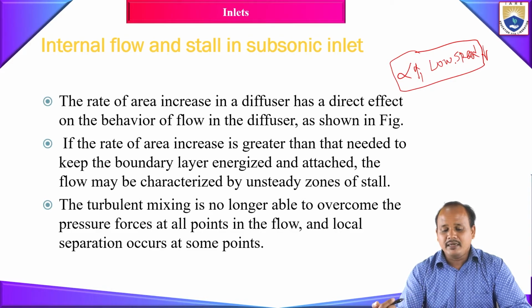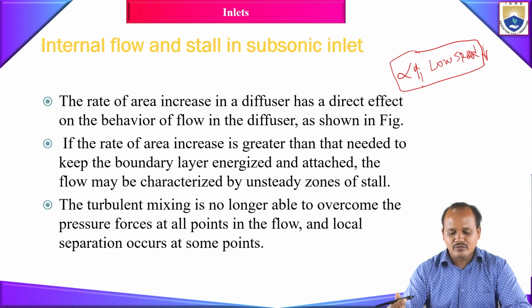Similarly, in the intake also, during your takeoff, we will have this flow separation problem, because during takeoff your momentum is already very low because your flight speed is low. If the initial momentum itself is low, when it is decelerated while passing through your intake, what is going to happen? Its momentum will be further reduced, which will result in flow separation. So we can clearly understand that separation or stall of your intake occurs during low speed operation, that is during your takeoff as well as during your landing.